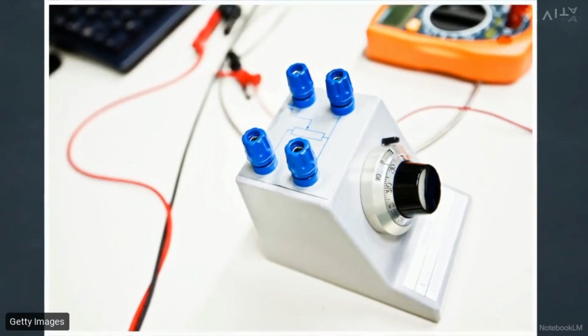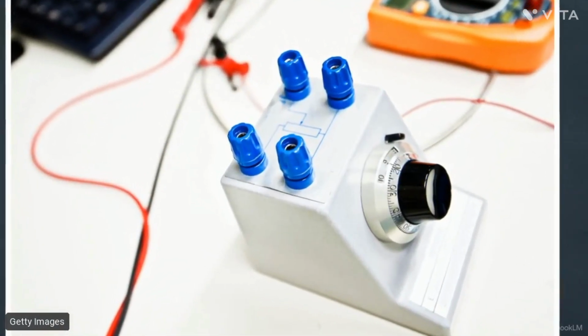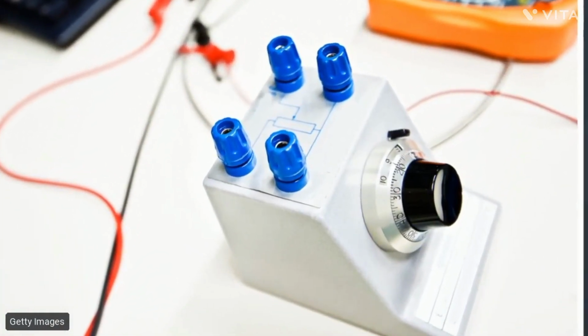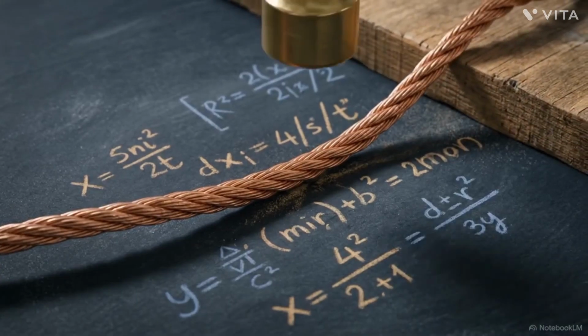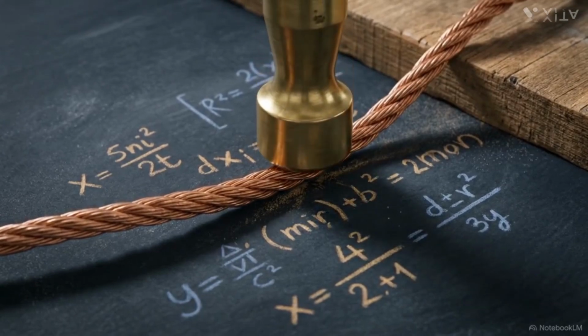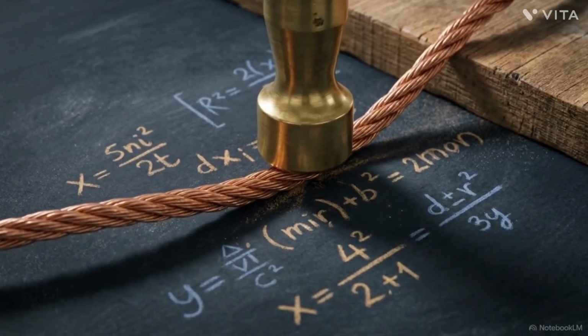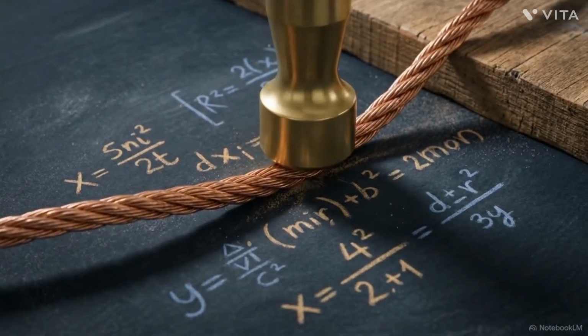These same principles are used in modern laboratories to find the internal resistance of a cell. Calculating internal resistance requires comparing the cell's EMF when no current is flowing against its terminal voltage when it is part of a closed circuit. The potentiometer finds the balancing length for the EMF, and then a second balancing length after a resistor is connected across the cell.